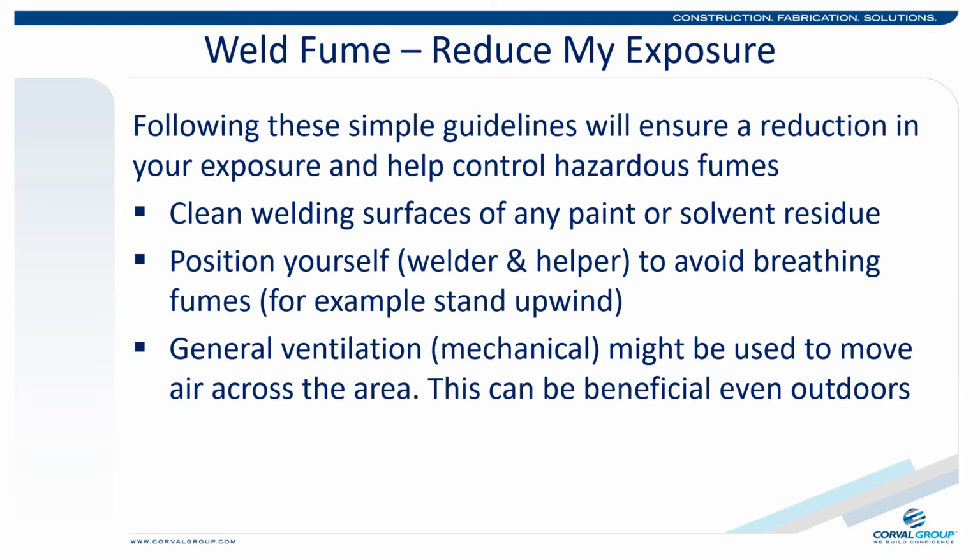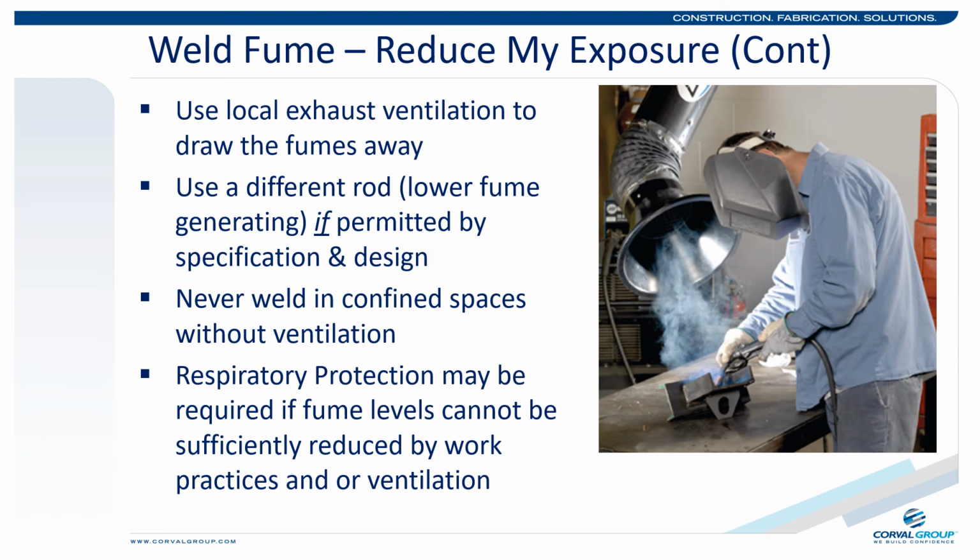Use general ventilation to move the fume away, thereby reducing your exposure, or by wearing a respirator. Local exhaust ventilation can be useful in drawing fumes away and discharging them at a safe distance away. When using local exhaust, make sure that fumes are not being discharged on others. Ventilation equipment is available through the Corval Group tool and equipment centers.